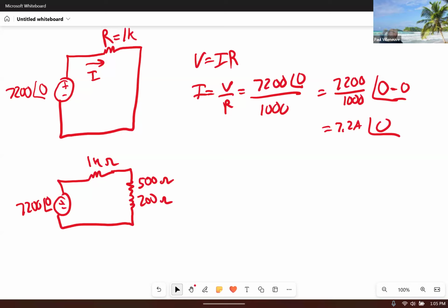Because it's L di/dt that is the voltage across it. So it's the rate of change of current. Once the current is not changing, meaning there's no current going in and out, there's no magnetic field, right? It goes to 0. So it's not like in a capacitor where you're integrating the amount of charge that goes in. Here I'm just differentiating. And since I don't get a changing current, if I take it out of the circuit, there's no current through there. So it's actually not going to work too well for us.